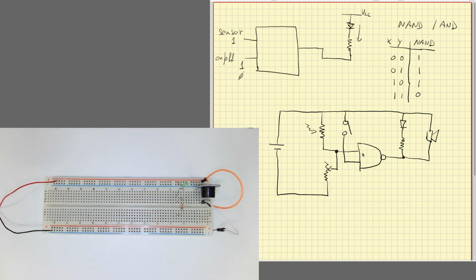Of course, this NAND gate has its logic inputs and logic outputs. This NAND gate also has to be polarized. We have to put energy into the NAND gate. When we design digital circuits, we don't make the power supply connection explicit. But in this case, it may be useful to know that we have to connect this to VCC, and we also have to connect the ground node of the gate to the ground node of our circuit. Okay, great.